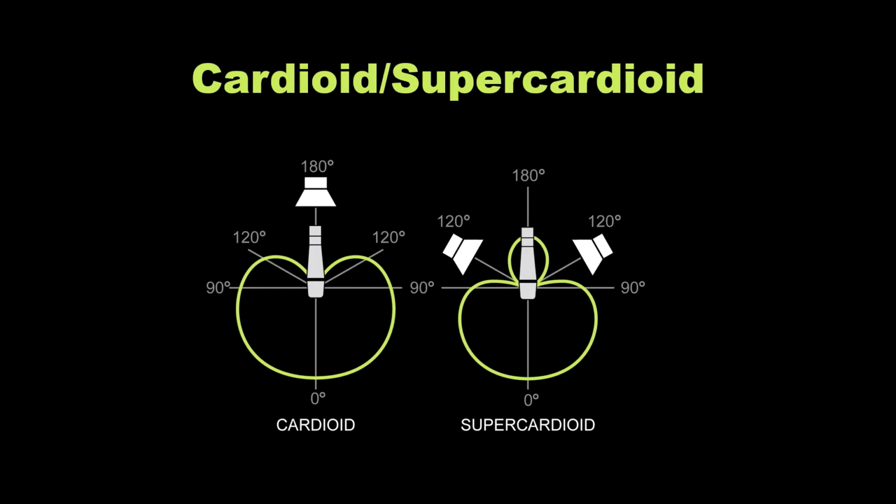Because if you place your loudspeakers for an SM58, which is at 180 degrees, and you turn it up to some level, then you unplug your SM58 and plug your Beta 58 in with that supercardioid pattern. Now the null is facing right down into the loudspeaker. So you might get feedback there that you didn't get from your SM58. So it's not that a Beta 58 feeds back more than an SM58. It's that you have to keep that pattern in mind when you're placing your loudspeakers.